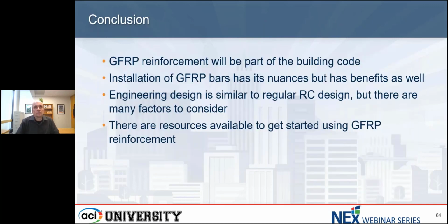All right, so I'll just conclude with a couple of points. First of all, again, GFRP reinforcement is now becoming part of the building code. So if you haven't used it before, if you haven't seen it before, chances are you probably will in the near future because it is becoming more and more common out there in our construction market. The installation of the bars is similar to steel. It is easier, but it does have its nuances that you have to be familiar with if you're out there working with it in the field.